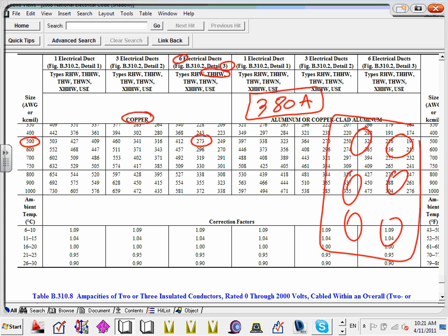273 amps. Any question, guys? So that will get you a bigger conductor size. You size bigger conductors when you carry the 4,000 amp. Now, based on this, guys, where's my calculator? If I have a 4,000 amp divided by 273 equals, I need 15 runs to size it.